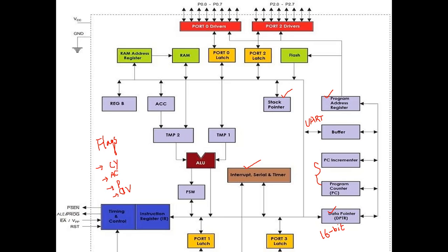Instead of using internal memory and internal available data, if you are performing an operation or application which communicates with external memories, then the data is not directly copied or accessed by the ALU into the temporary registers. First it is accessed into the data pointer, then into the temporary registers, and then you can perform the various operations or applications.